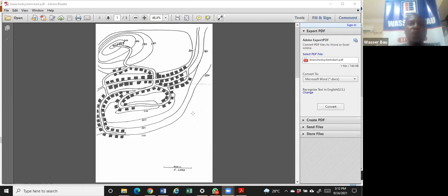And get the best out of it. So when you are given information like this, a map, the next thing you should require is to get the elevation information, or you send your surveyor to go and take levels. You need those levels because the first thing you need to do is to determine where to site your overhead storage tank, since you're going to supply the water via gravity. So your point would be, where is the most convenient place vis-a-vis safe and elevated? For you to have this information, the surveyor must go to site and determine those parameters.